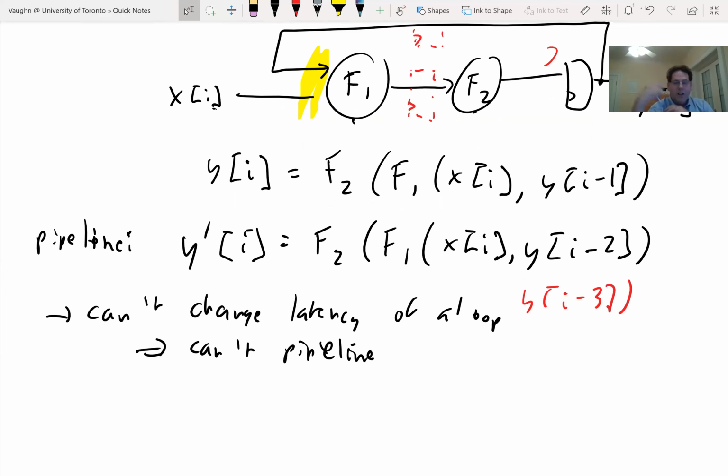There are 2 basic kinds of filter. There's a finite impulse response filter where your outputs only depend on your inputs, and there's something called an infinite impulse response filter where your outputs depend on both previous outputs and inputs. And generally people prefer in hardware finite impulse response filters because they're easier to pipeline because they don't have these dependencies. So people try to get rid of their loops when they can, making it easier to pipeline and get higher frequencies. You cannot get rid of finite state machines from your entire design, right? So you're going to wind up with some loops generally in your control.